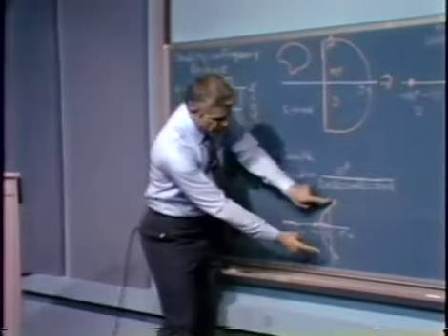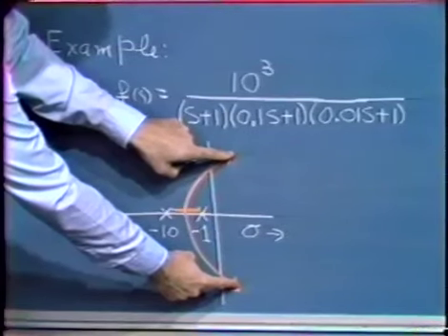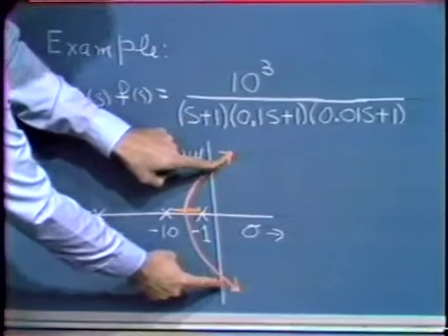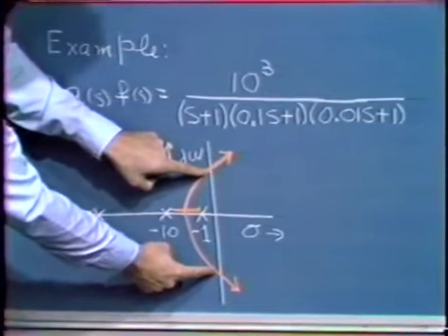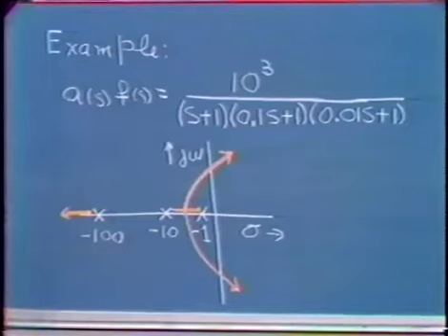where we start at a high loop transmission magnitude, a high A0, F0 product. We have two poles in the right half of the S-plane. We lower A0, F0, and eventually the system becomes stable. So we see exactly that same behavior, as we must, in the root locus presentation.